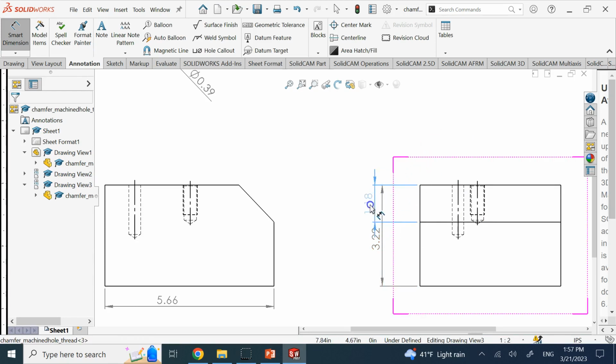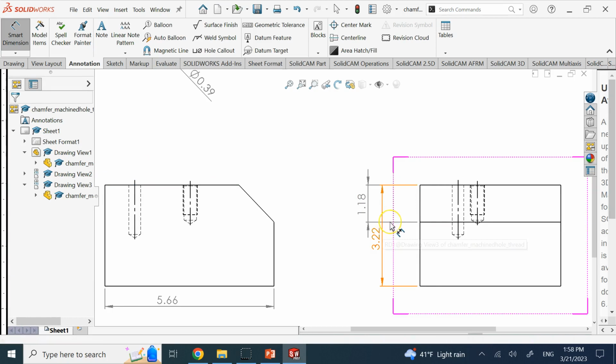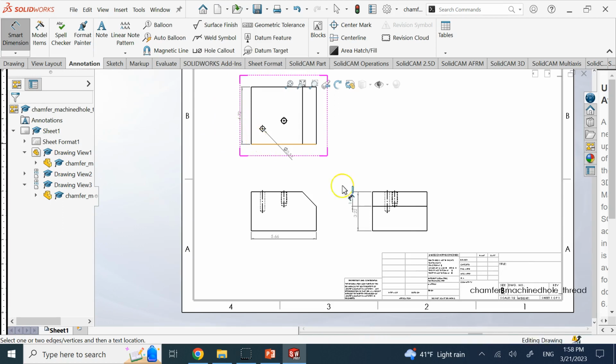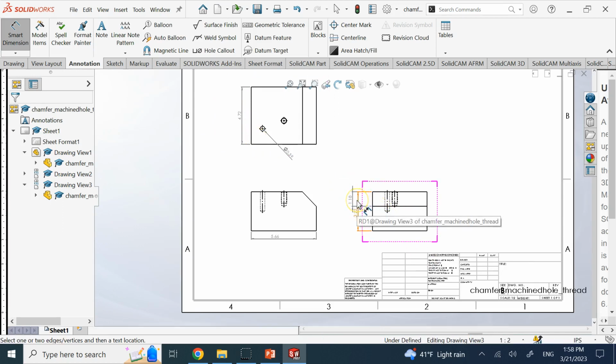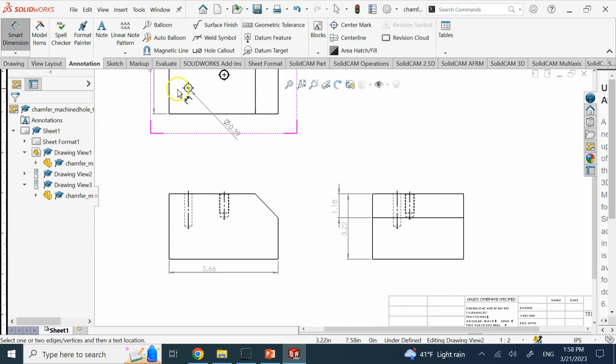But there are some scenarios where it's too crowded and there are too many dimension lines and it's very hard to get it. Is that a fundamental mistake? No. It's not like two dimension lines are crossing each other. If an extension crosses another extension or an extension crosses another dimension, it's not as fatal, but we try to avoid it the best that we can. We try to avoid all intersections, but dimension and dimension is absolutely prohibited. Okay, so keep that in mind.